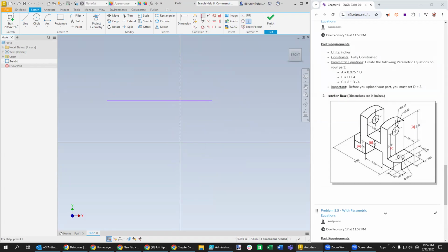And then when we want to center this up, we can go like that, and then control click right here, and we've made those centered up. Another way to do that, hit Control Z a couple times, is we're trying to get this new feature for everybody that says midpoint on all these computers. If you don't have that, you'll have to do it the other way, but look at this midpoint control. I don't like the fact that it was not letting me make it horizontal, but there we go. And the distance that we want this one to be is going to be 1.25 inches.